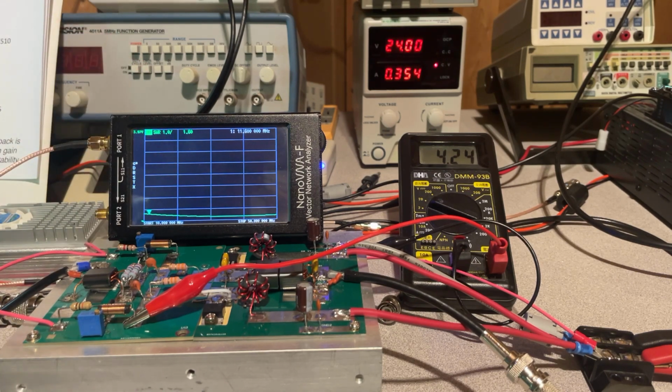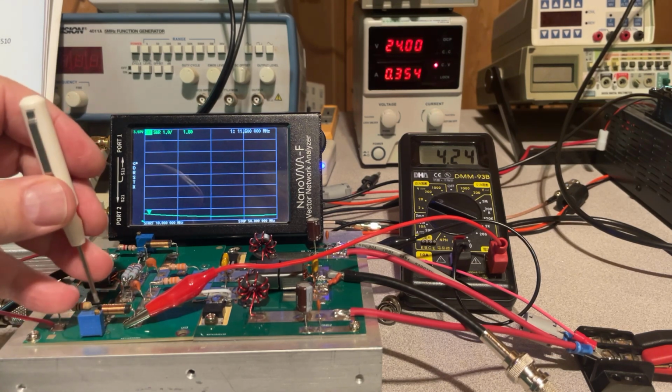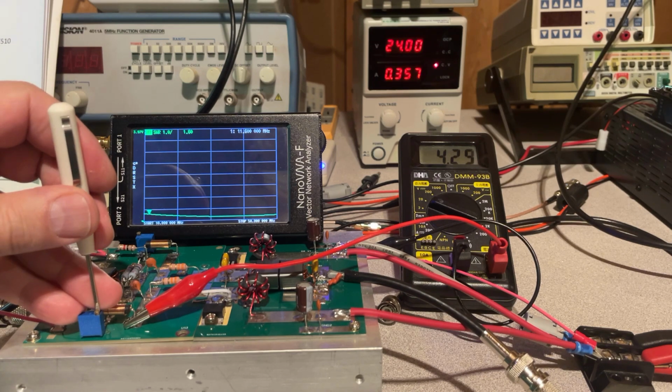And in this circuit, we have basically a voltage divider. So we have a 1K resistor and a 10K potentiometer. This makes up a voltage divider. Then here's my Zener diode that I use to regulate 24 volts down to 12 volts and provide temperature compensation. And then this is just a small RF choke that drives the gate of the transistor through the dampening resistor here. So let's go ahead and, while we measure the voltage, adjust the bias voltages.